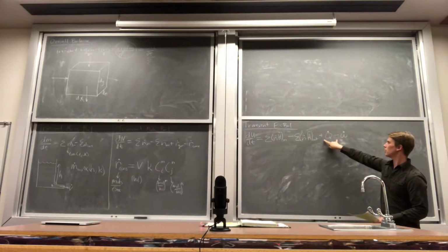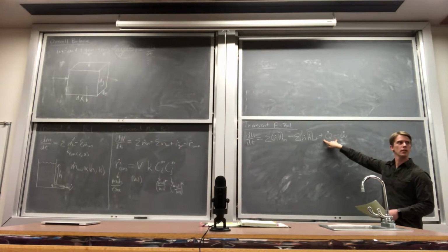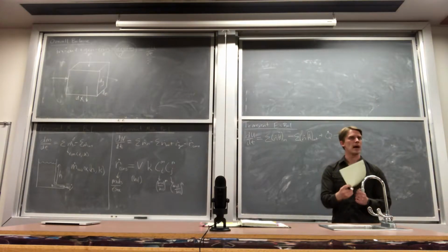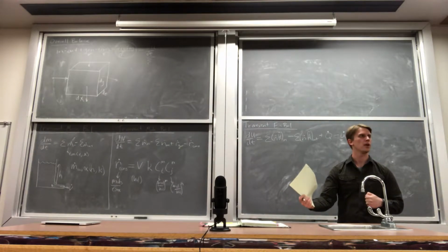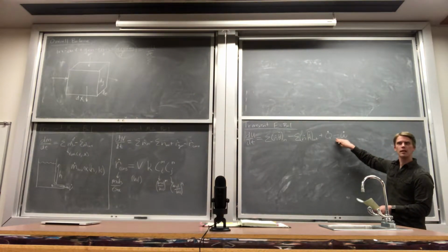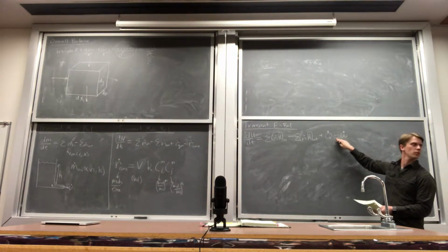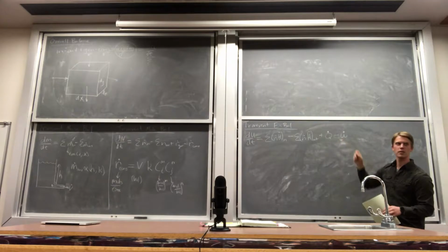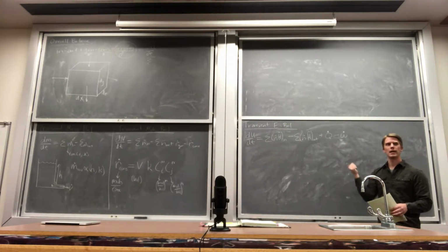Now, the conventions here are not strict, but just remember, do the plus and minus arrows based on how you draw your process. So if you have a heat exchanger, energy has to be minus at one and plus at the other, otherwise it's going to mess things up a lot. So a lot of people will fret and worry over positive work and negative work, and there's textbook wars over which is the best way to do it, but ultimately I don't think it matters. Just draw it. If you draw an arrow into your system, you plus it into your balance. If you draw an arrow out of your system, you minus it in your balance.